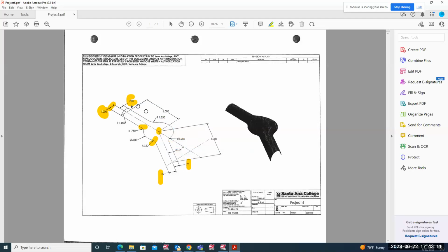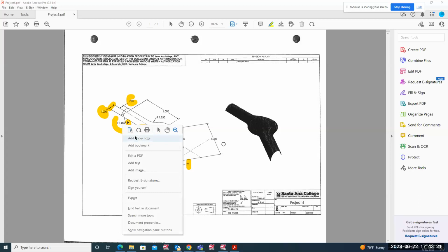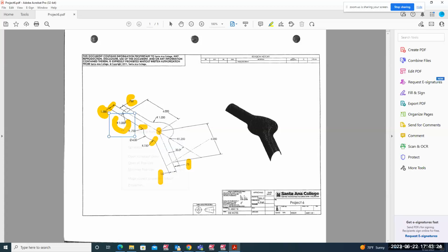All right, now we have to do this arc over here, radius 1 inch arc, this guy right there. So how can we create that arc? We have to go to construction plane. This was my top plane. This is my right plane. And for the right plane, what's going to be my Z is minus 6 inches from 0. So let's go to construction plane right, and we're going to create this 1 inch radius arc. This is the start point, this is the end point right there, and the radius is 1 inch.